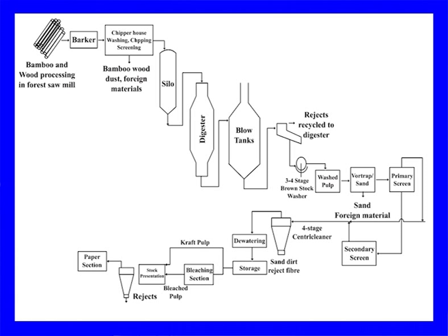After your cooking is completed, it is blown in the digester, and after the blowing it goes for removal of rejects and fine knots, and then to 3-4 stage washing. The washed pulp that we are getting goes to the screening section, centri-cleaner, all those things that we use there for removal of fine dirt that may adhere. After chipping it goes to the cyclone also, but some of the silica may still be there, and so that has to be removed before it goes to paper making.